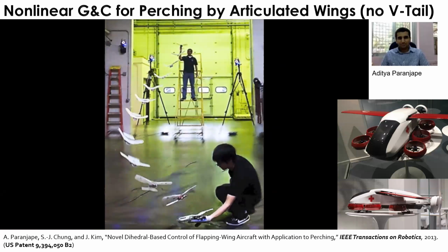One idea is that any aircraft has a time delay. You want to turn, but then there is an actuator delay. So you're going to move a little bit forward and then turn. So we usually take into account this kind of nonlinear time delay in your dynamics. And then you develop this kind of pursuit evasion, like a Dubins vehicle motion planning.